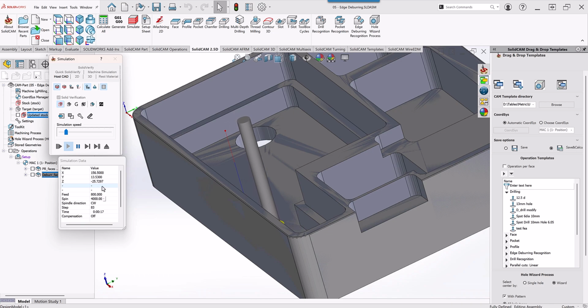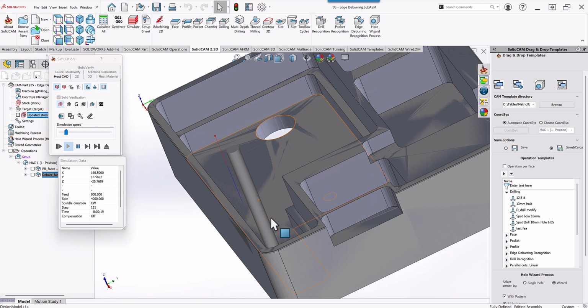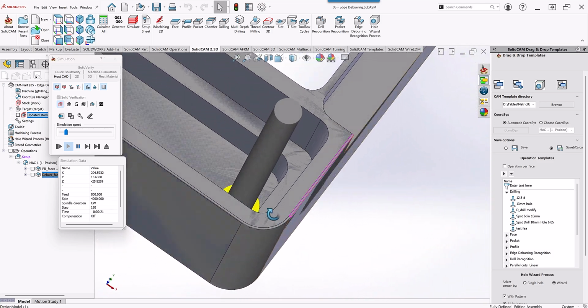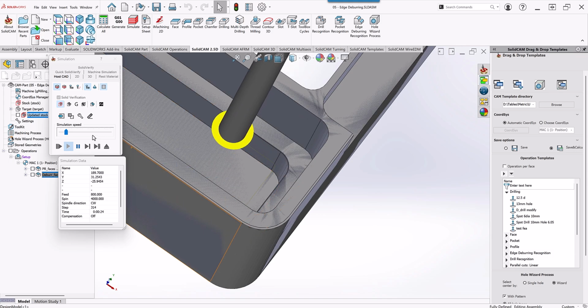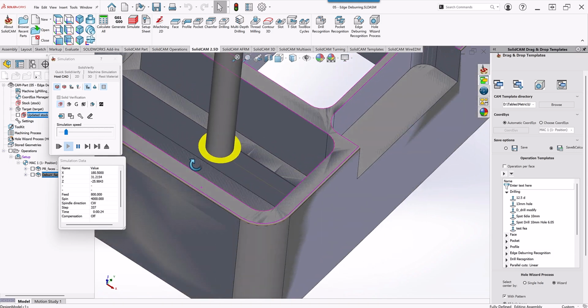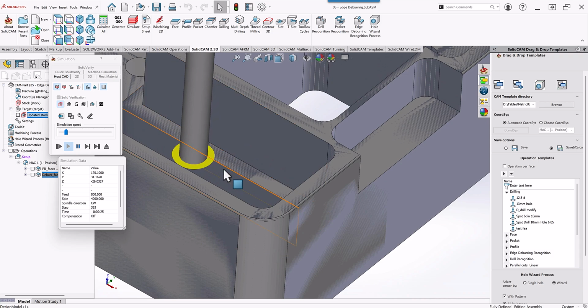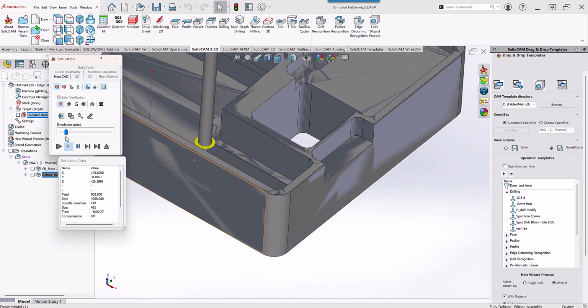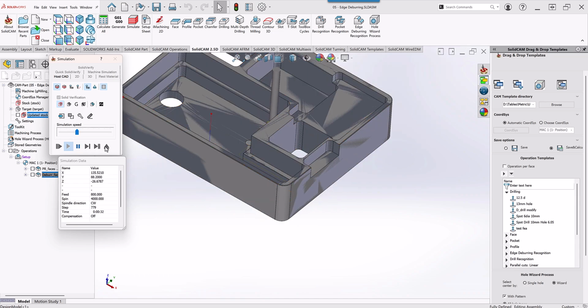However, as it starts going around, you'll see that that Z level is constantly changing. It's going further and further down, and that's because the actual cutting diameter is getting larger. So when it gets larger, it means it goes further and further down on the part. But the actual chamfer that is creating on this will be equal all the time. Let's do this now a little quicker, and we'll also see this at a certain point when it gets to the top. You'll be able to see it a lot better.